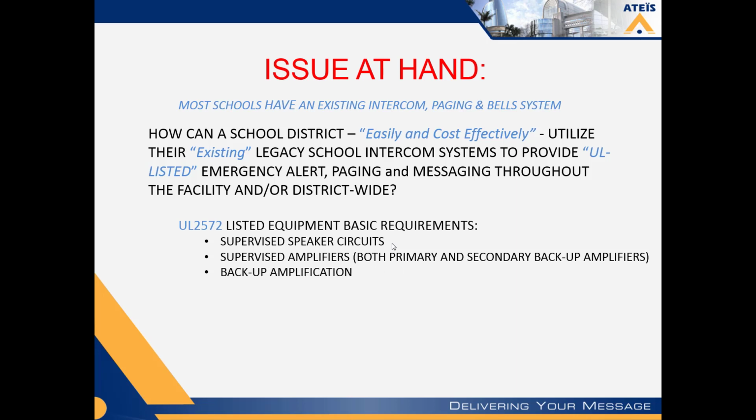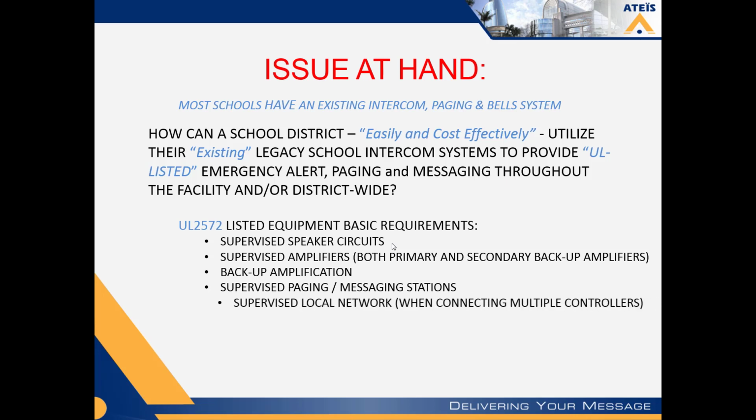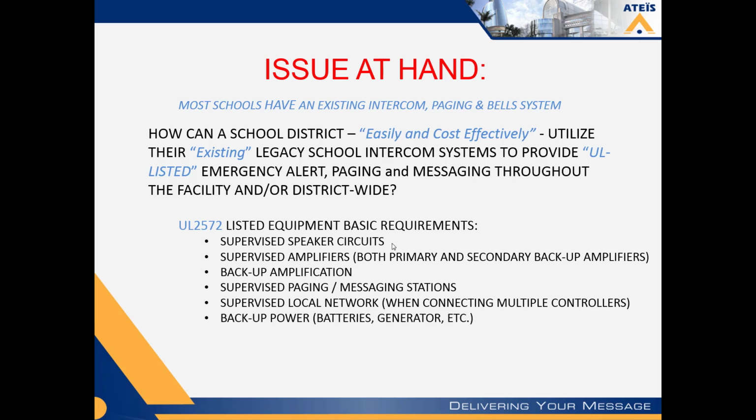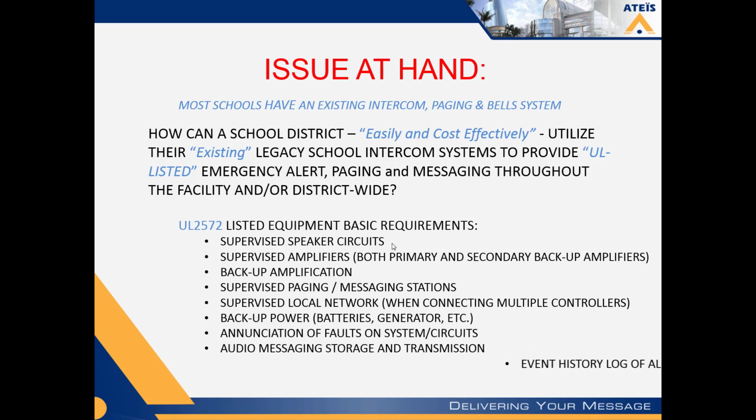They have to supervise all the amplifiers used in the system, and you have to have backup amplification capabilities as well as supervise those secondary backup amplifiers. Any paging and or messaging stations connected to the system must be fully supervised by the system, and that must be able to handle backup power, whether it's direct with battery chargers and power supplies on the system, and or sometimes you can get away with just putting on backup generators or emergency power with the facility. Healthcares do that a lot.